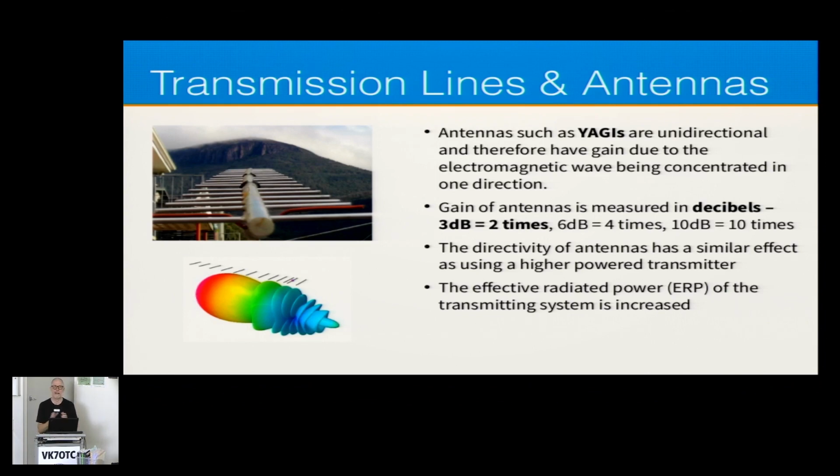Now, there aren't that many antennas around that give you, apart from probably dishes, maybe, a scary amount of gain. So 10 watts, don't worry about it. You're not going to get to a point where it's scary. At 400 watts with a dish, you probably would get to some scary EIRPs. But for a foundation licensee, with only 10 watts to use, this could be quite advantageous.